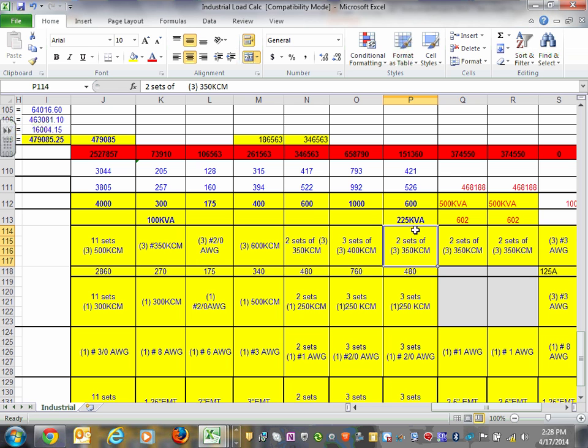For the 600 amp panels, that's one of our panels, we have 2 sets. Same thing for these. For these guys, I size them strictly based on 600 amp. And the reason why I did this one is because I had a question one time from a guy: well, where's the 1.25 for continuous load?